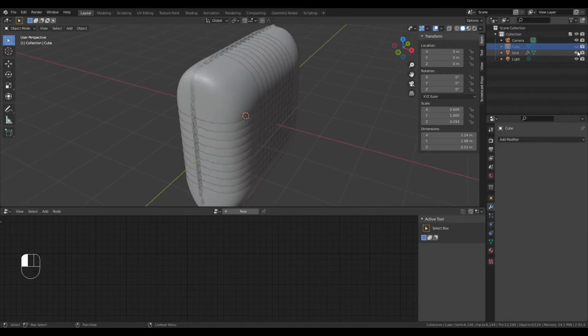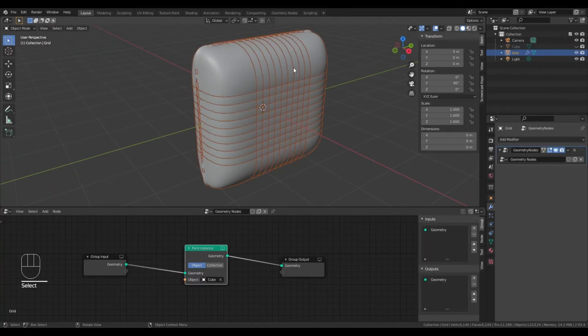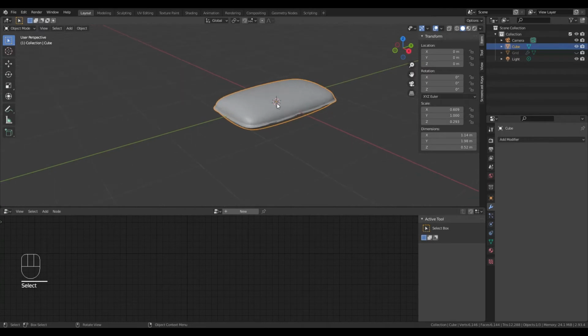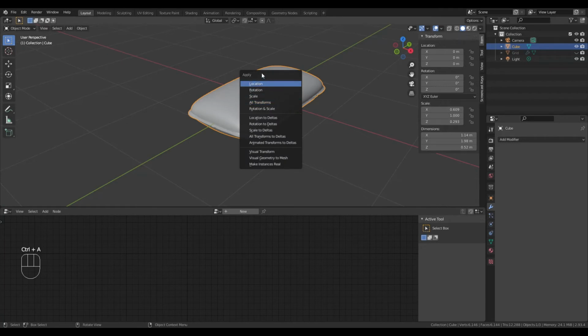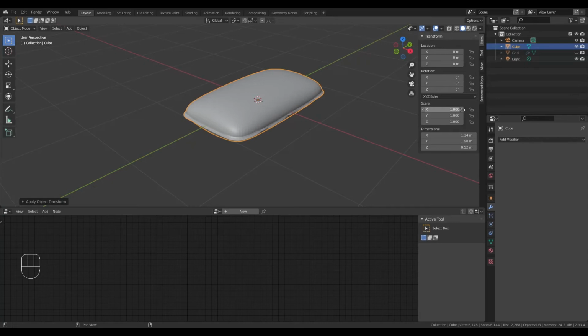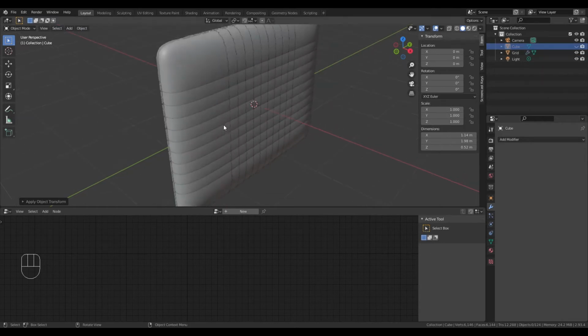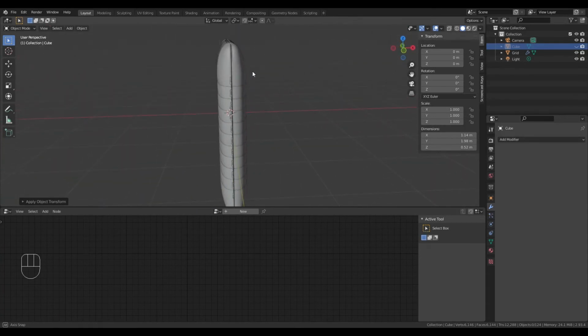When we look back at the grid, Blender is applying a scale of 1, 1, 1 to all of the objects that it's outputting. So in order to tell Blender these are the actual dimensions that we want, we're going to do Control A, and then in this Apply menu, we're going to click All Transforms. So that's changed our scale to 1, 1, 1 now, which means Blender is now respecting it. So I'm going to hide the sandbag again, show the grid, and now you can see that the sandbags are a bit less giant, a bit less thick.